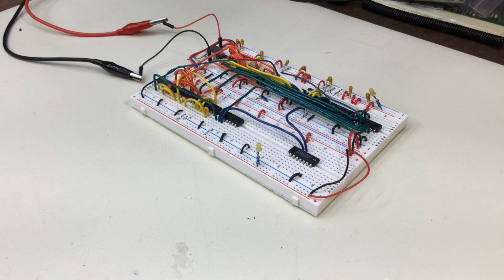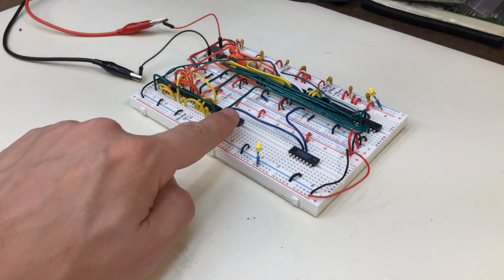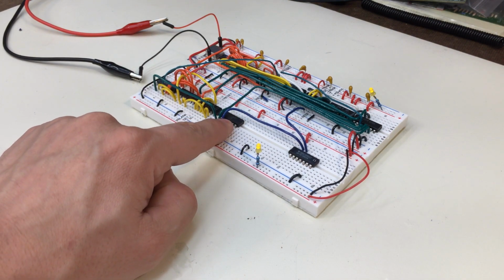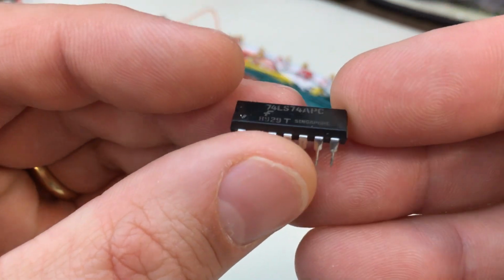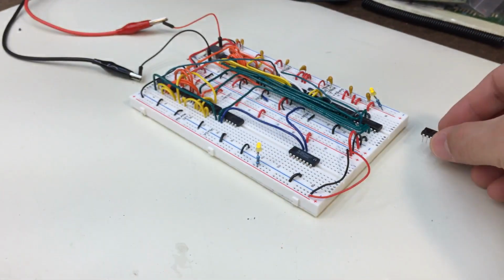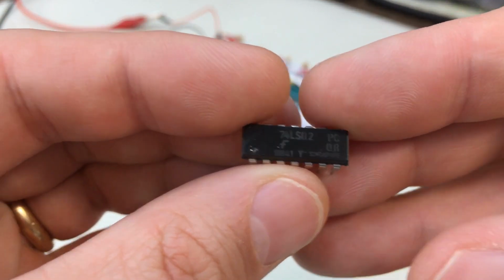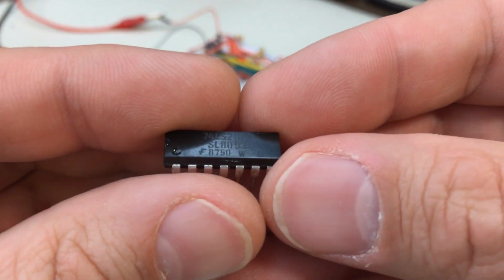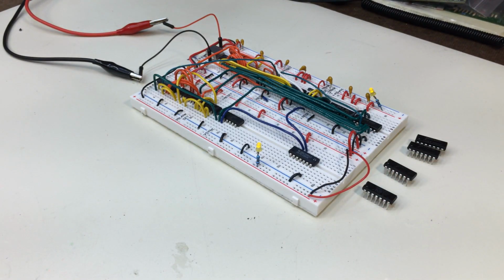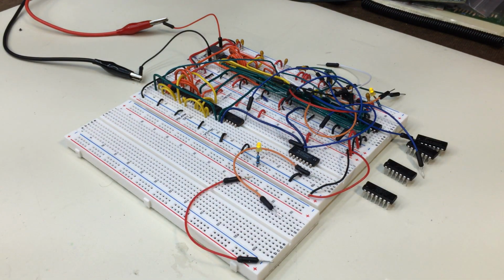Here's what you'll need for this phase of the project. The previous work and power supply. The 74LS32 chip we added to fix V-blank. Two 74LS74 dual-unit D-type flip-flop chips. One 74LS02 quad-unit NOR chip. One 74LS20 dual-unit quad-input NAND chip. Another solderless breadboard, and connecting wires.